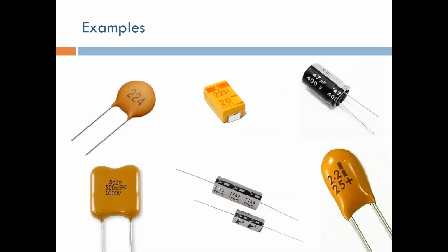Okay, so make sure when you're using a capacitor with polarity, or when you have a rated voltage for the capacitor and you're using something that is close to that rated voltage, you should be very careful. Usually, if you have 100 volts in your circuit, I would suggest using 3 times that much for the rated voltage of the capacitor. So for example, if the maximum voltage in my circuit is 100 volts, at least a 300 volt capacitor should be used, not less than that. You don't want to be at 120, for example.